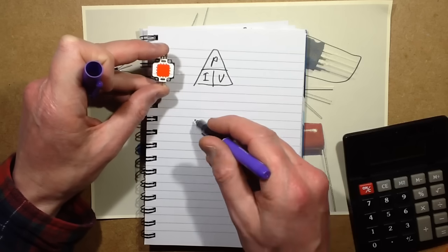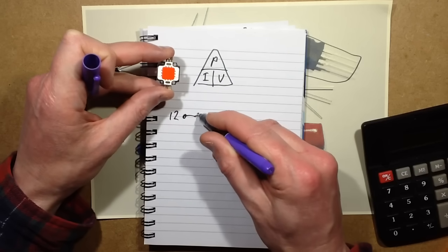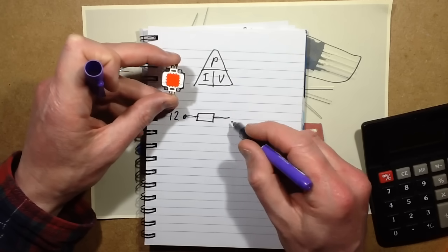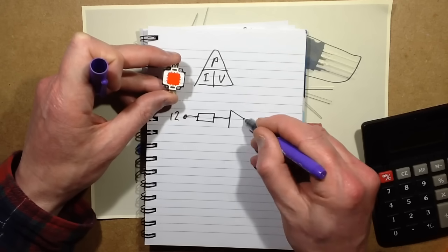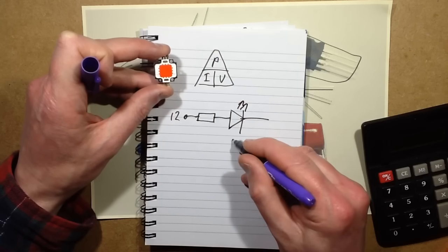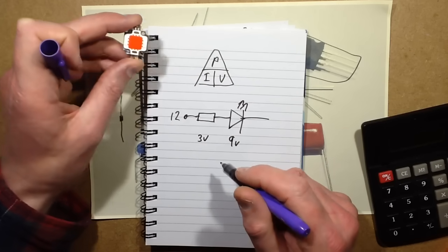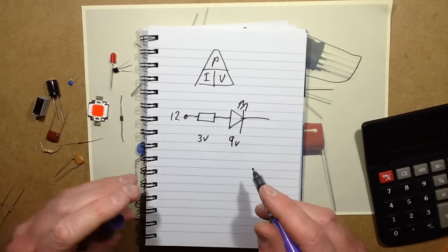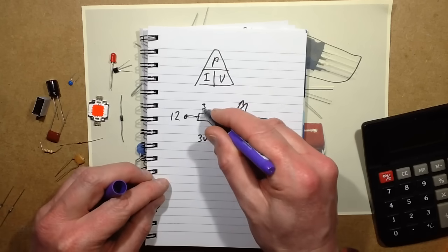So to calculate, if we were to actually put a resistor on a 12 volt supply again, and choose a resistor to limit the current through this to the 1 amp. So let's see, I'll just draw it as a huge big LED. I'm not going to draw what's in it. There's a 3 by 3 array, but the voltage across that is about 9 volts. So we get 3 volts to drop across the resistor. And if we go back to the original formula, R equals V over I, we've got 3 volts divided by the 1 amp we need, so that's going to be about 3 ohms.